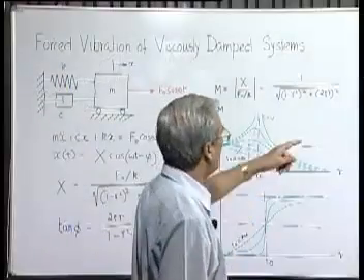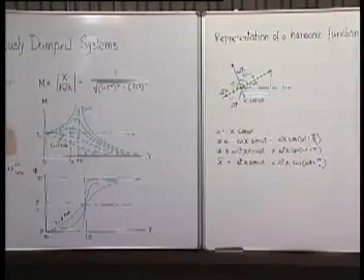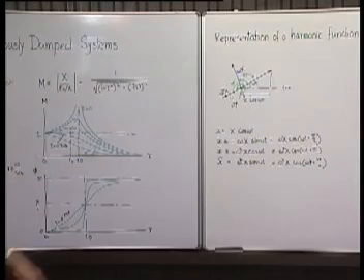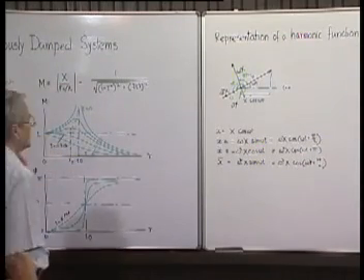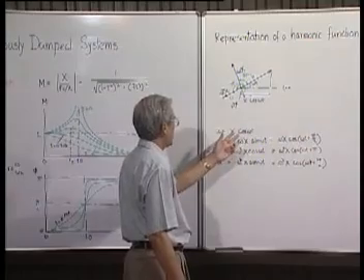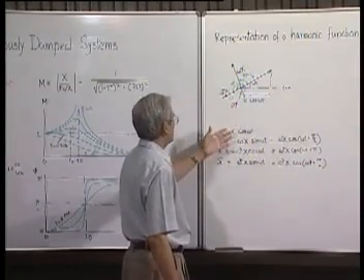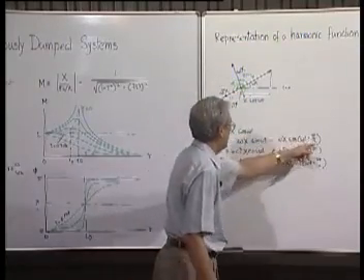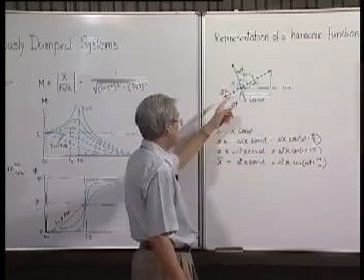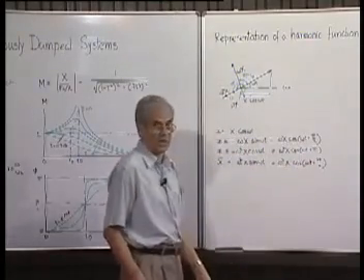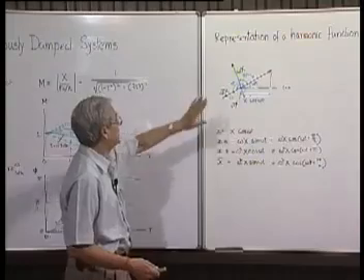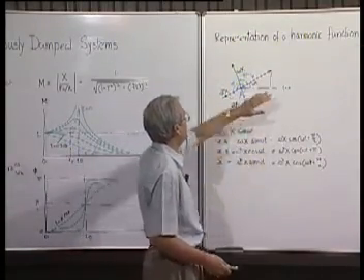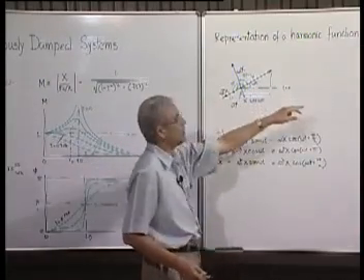So when these four vectors rotate like a rigid body with an angular speed omega, their projections on that line, t is equal to 0, will be harmonic functions of time. This will represent the position, then this will represent the velocity, this will represent the acceleration, and this will represent the jerk. So therefore these vectors do not have any physical existence. All the time we have to keep in mind that only the projections along this line are what we have in reality.